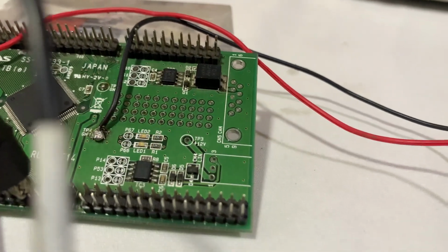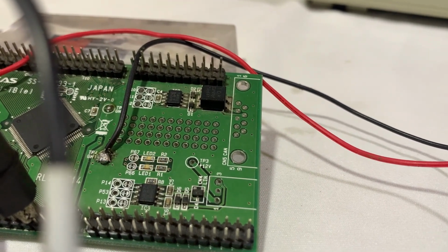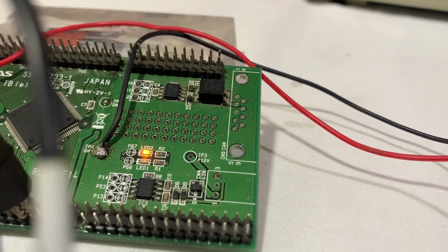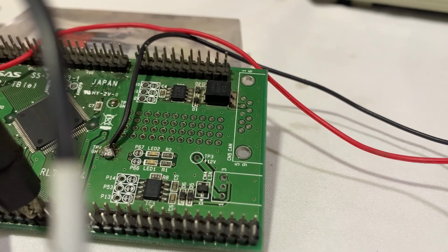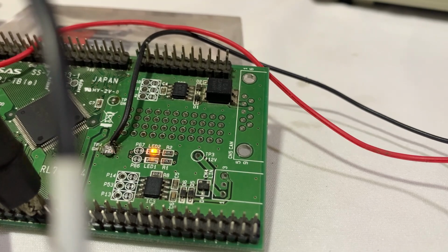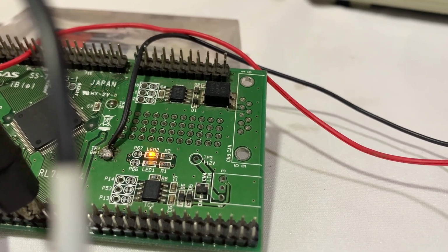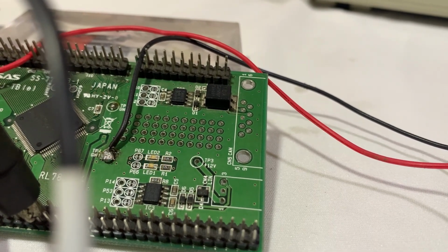You can see this is the output which we got for 75% duty cycle pulse generated. Since this LED will be turned on only when providing a low signal, on increasing the duty we will get the LED dimmed, and on decreasing the duty we will get the LED lighted up properly.